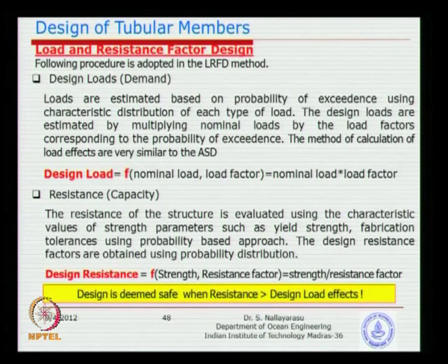For example, live loads: you design for a residential building versus a public building. Typically you take the case of a table or a chair. When you design for a residential building, you could use a lesser value, because the potential variation of loads could be very small. But for the same table or chair, if you are designing for a public building, it could have a higher variation because of change in loads. The characteristic loading could easily change.